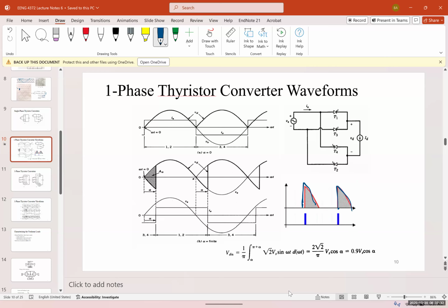Now, what advantage does this give us? It gives us control on how much power we want to deliver. Sometimes we don't want to convert 100% to the output. This acts like a switch as well. You can convert 50% of it or half of the signal. This is for an ideal one. Yes, thank you for bringing that up. In the real world, you have several volts drop for the output, and you have a delay as well. It doesn't trigger at the moment that you give it a control signal. So this is, obviously, for an ideal one.